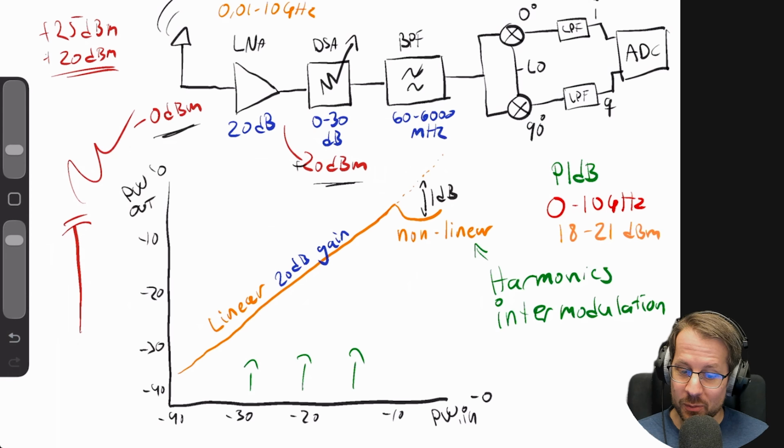But before that happens, your LNA will go into compression if you add too much power. So the LNA can have a breakage point at plus 20 dBm, but it can start to go into compression at -5, -10 dBm, and then it will start to produce harmonics and intermodulation in your spectrum analyzer, so your view gets completely distorted, right? So that is really, really important to know.